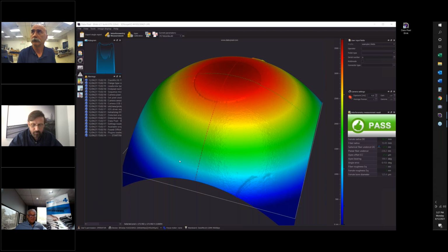So one was, when I looked into doing the SMPTE connectors, I realized I had to spend $30,000 to start. I was curious, how long does it take you to typically put on a SMPTE connector, the 311? Start to finish, if you do them in lots of 10, set up with prep, you get a completely different animal if you sit down and try to prep one connector. One connector is going to take you 2 hours, 2.5 hours. If you do them in lots of 10, you're going to average about an hour, 15 minutes, an hour and a half to put one connector on.